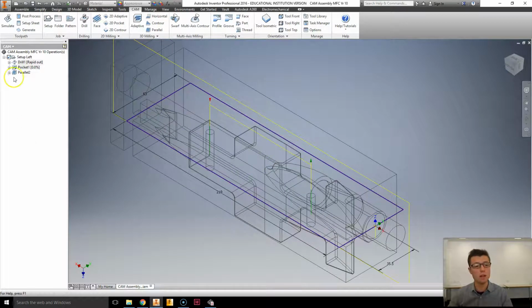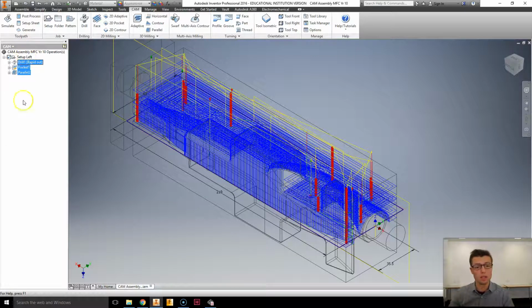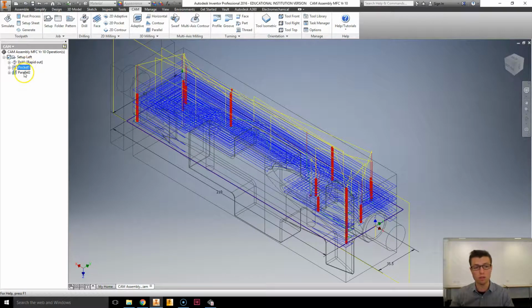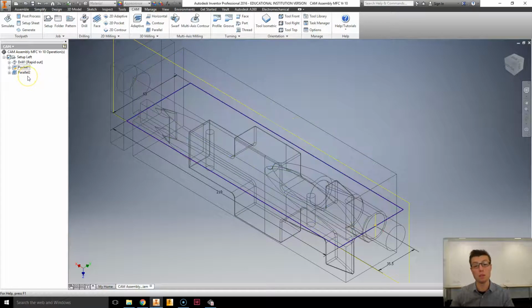So this is the toolpath. So once these are generated, you'd want to select both of them and using the snipping tool, take a snip. Once this is done though, we'll actually simulate it and I'll show you a few things to look out for. The simulation actually allows us to check, once you specified fixtures, whether or not you're going to hit the fixtures with the bit, the cutter. And obviously we don't want to hit the metal fixtures, so that's quite an important step. Selecting them all here, this will be one of those options to take a screenshot. In your folio, I'd certainly be specifying what each of these toolpaths are and their purpose.